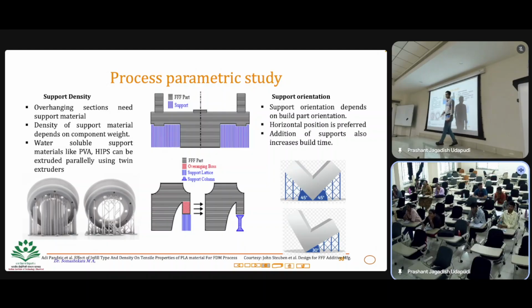For example, you think about you have one layer like this, right? So for another layer, if you want to extend without support structure, you can build something like this, right? So now you are taking advantage of a previous layer, then you are laying other material, so that you can see how much angle you can go without support structure, right?